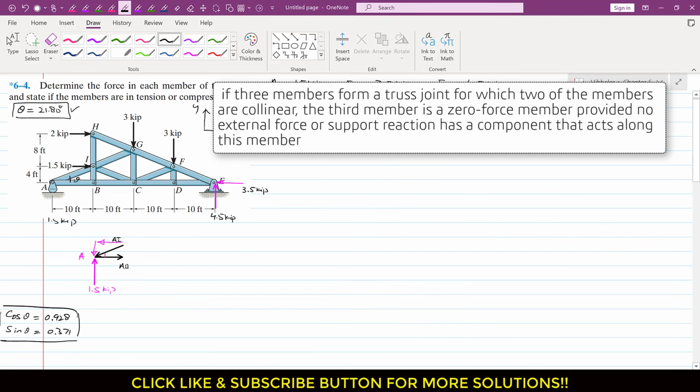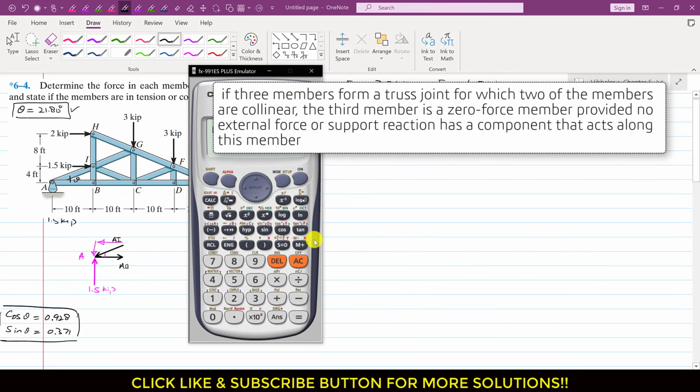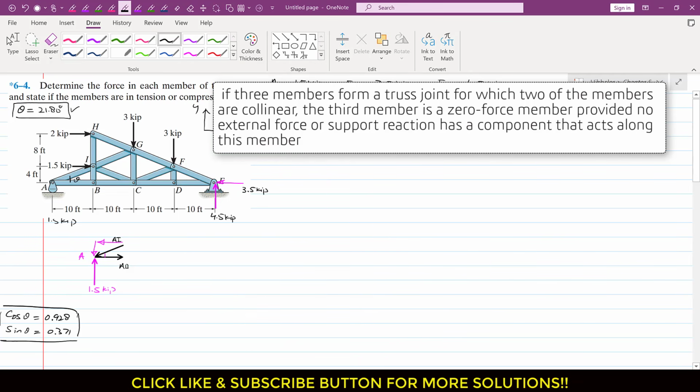So this is into 4.04, and this will be equal to 0, or we can say that AB is equal to this thing, right? So AB is 3.75, right? So I will write that AB value is 3.75 kip, and since AB is acting away from this joint A, this means that this is the tension force, right?